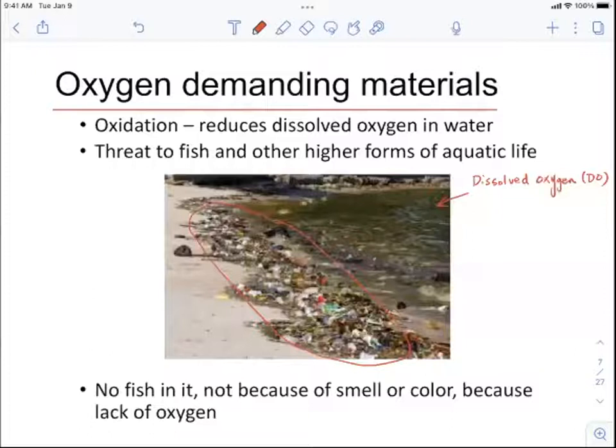So if you can imagine, let's say we have a 1 liter container, for example, a kettle at your home. If you have 1 liter of fresh water, and we put it under 25 Celsius and 1 atmosphere, the maximum oxygen that can get dissolved in this 1 liter of water is just 8 milligrams. So basically the maximum dissolved oxygen is 8 milligram per liter, okay?